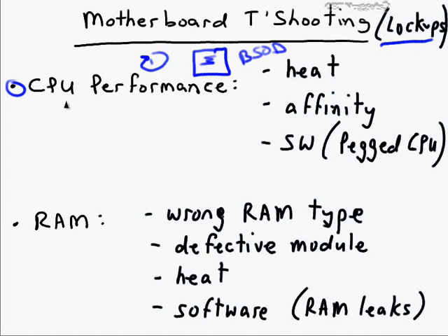Specifically, let's now look at processor performance. Some things that we're looking at in terms of compatibility and performance are excess heat. Your CPU is going to be generating too much heat and putting not only itself at risk, but other motherboard components if, for instance, the technician has not adequately researched the capabilities of the underlying MOBO or motherboard.